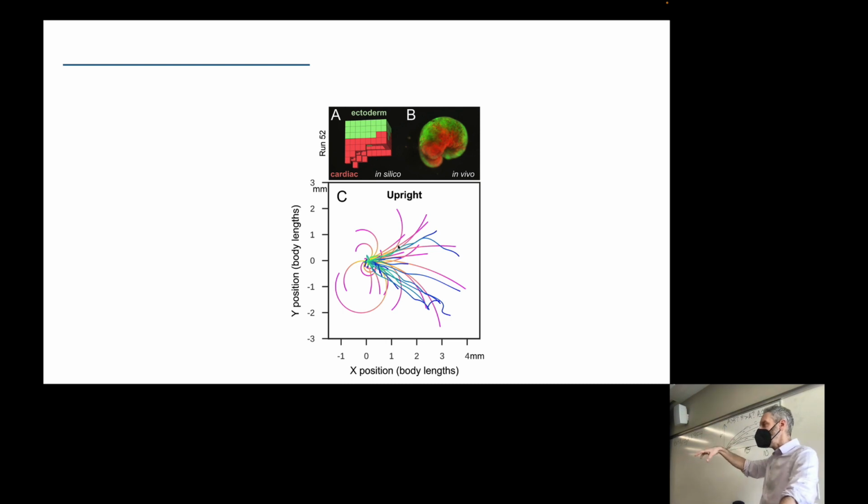We replayed the same simulated Xenobot multiple times, and it produced different trajectories. Why do you think that occurred? Same Xenobot, exact same design, produces different trajectories. It was like the offset was randomized, and so was the amplitude of every part cell. Yep, not the amplitude, but we randomized the phase offset. Every voxel in every simulated Xenobot has the same frequency, same amplitude, just we randomly set the phase offset at the beginning of each simulation, and then hold that phase offset for the remainder of that simulation, which produces these different curves.